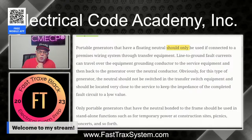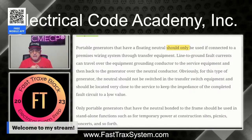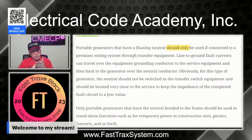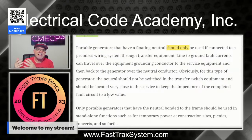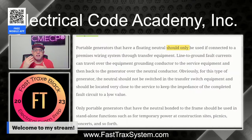One of the biggest things that I always run into with people is when they do a generator for their house and they determine whether or not, depending on what happens in the transfer equipment, right? If the transfer equipment switches the neutral on it, okay, just breaks the neutral, then what you have is a separately derived system, okay? Now, if it doesn't switch the neutral, then it's not a separately derived system, okay? So it's important when you're selecting the equipment to know what you're doing. But don't worry, we're going to dig even deeper. We're going to look at this, okay?